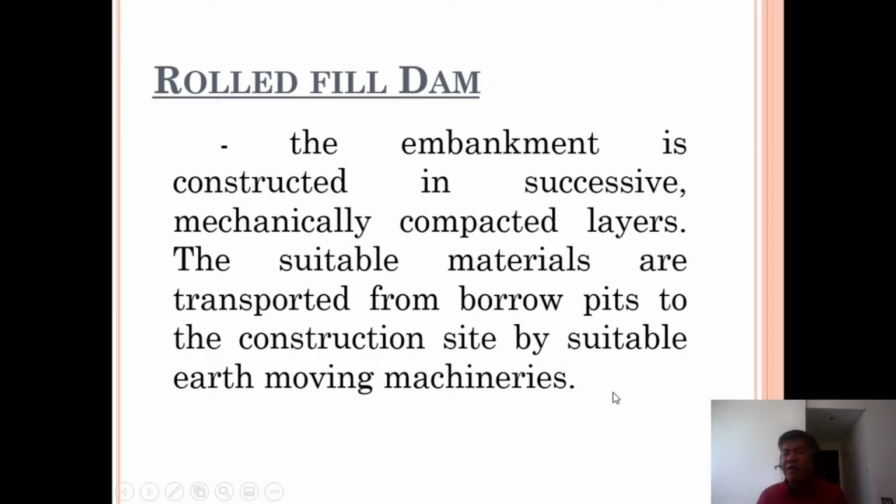Of course, in terms of layers, there are a lot of standards to be considered. Maybe some of you will be asking how thick the layers are. Some use 300 to 500 millimeters, or 0.3 to 0.5 meters, then have it compacted. So it depends on the method of construction, from the method statement as approved by the Quality Assurance Department.